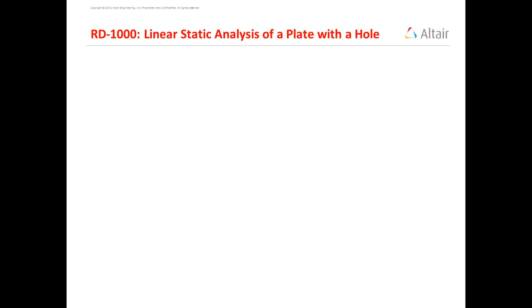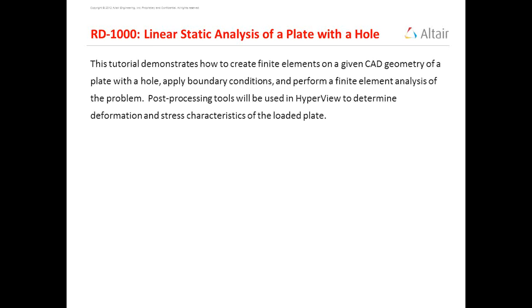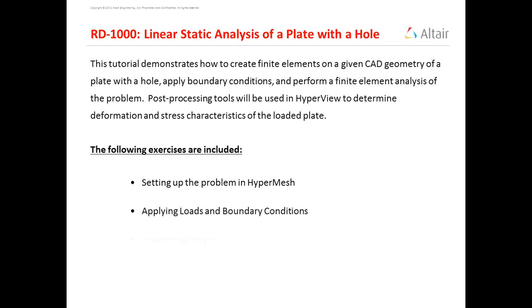So we will start our session with linear static analysis of plate with hole. This tutorial demonstrates how to create finite elements on a given CAD geometry of a plate with a hole, apply boundary conditions and perform a finite element analysis of the problem. Post-processing tools will be used in HyperView to determine deformation and stress characteristics of the loaded plate. The exercise includes setting up the problem in HyperMesh, applying loads and boundary conditions, submitting jobs, and lastly we will see how to view the results.